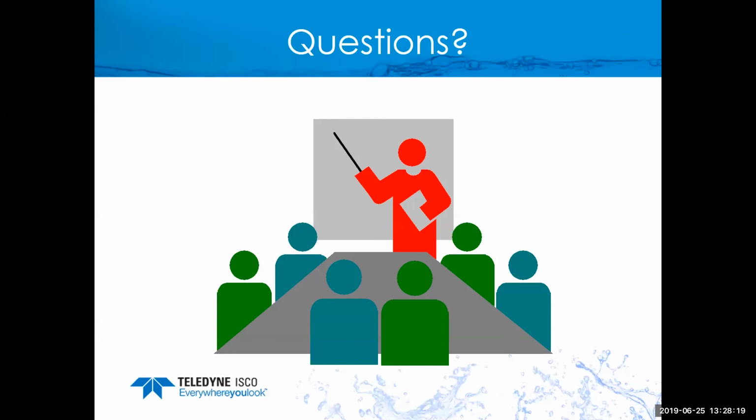Let's see. Okay, looks like the performance of the meter is great. The most difficult part is going to be installation. As industrial pretreatment, I'm going to be MacGyver and wondering what types of monitoring equipment. Most manholes have step downs, maybe something that can mount to those steps. You can get very creative.